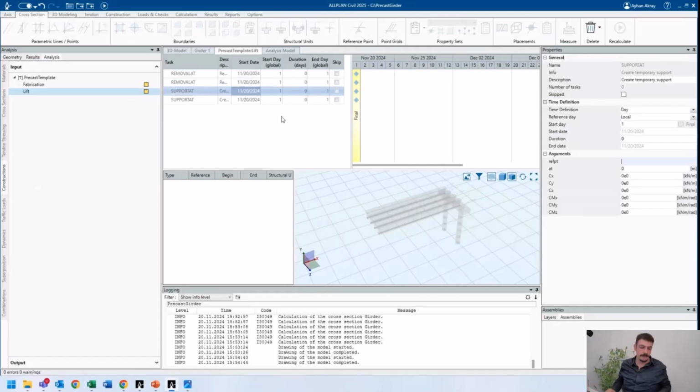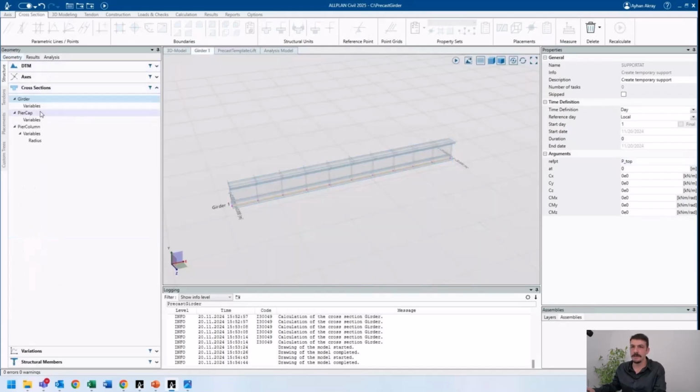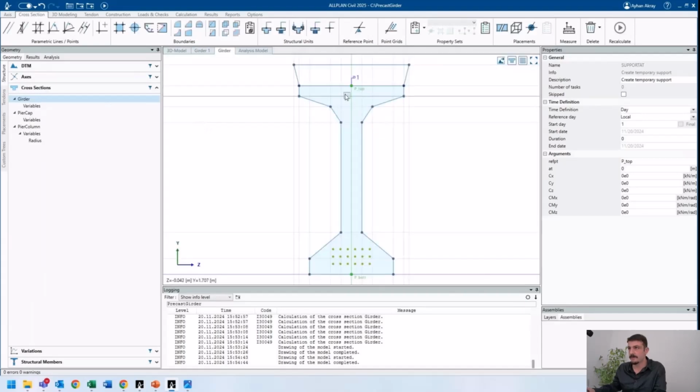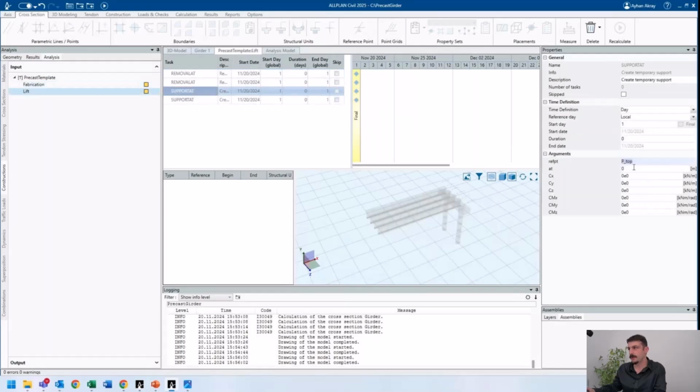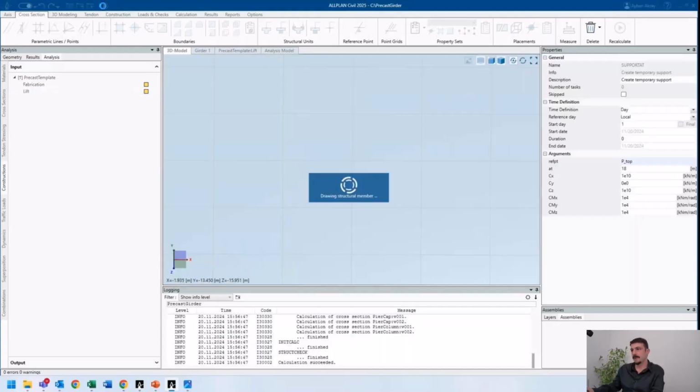And again, for the lifting process, I can now change my reference point. As you may remember from the girder, from the girder code section, the top reference point was this, and I can go and assign again, this time, for example, the second station, and again the rigidities as we design. I would like to again have pin support for this with some rigidity in the rotation, not the last station but the station before the last one. And I would release one translation for roller support, pin to roller connection, and recalculate our model again.